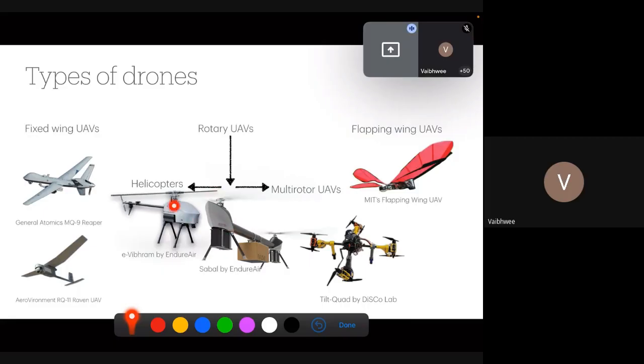You see that it has 2 main rotors. So this can also be classified as a multi-rotor UAV, but the actuation system that it has is similar to what the actuation is on the single rotor of a helicopter. So it is a kind of hybrid between a helicopter and a multi-rotor, where there are 2 main rotors at 2 ends, and the actuation system is somewhat similar to helicopters. It has no tail rotors in this case, and all the attitude and position are maintained by controlling these 2 rotors.